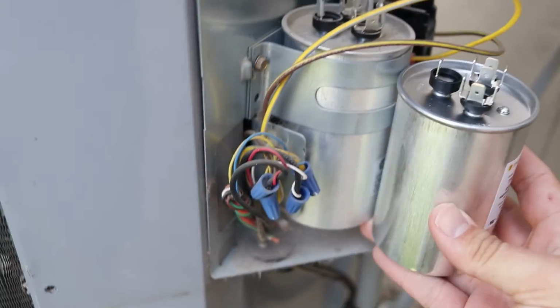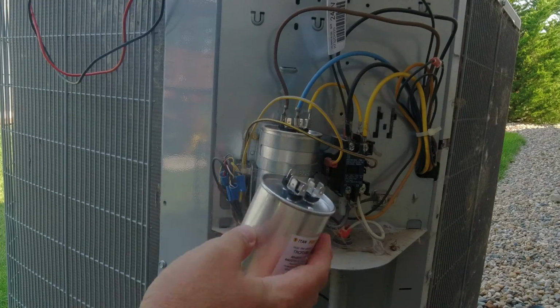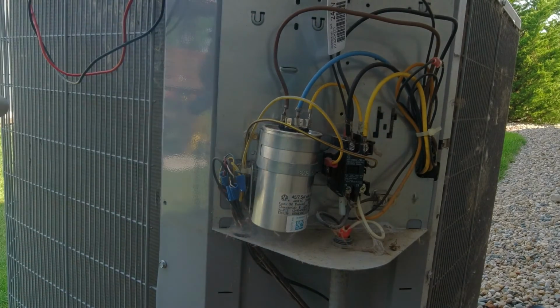Like I said before, when you're dealing with capacitors, one of the first things we need to do is remove the terminals that are connected to the capacitor. So make sure the first thing you do is take a picture of the capacitor before you do any work. This way you have something to refer back to if you make a mistake later on or forget. I'm going to take my phone here, snap a quick picture just so I know the color codes and where everything goes. So now I'm going to loosen up the bolt on the side of the retention clip, and then we're going to go ahead and swap it out for the new unit. So pretty similar, same type of lugs. So we're just going to move all those terminals over.